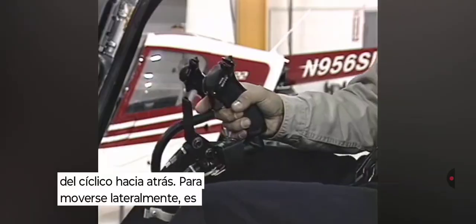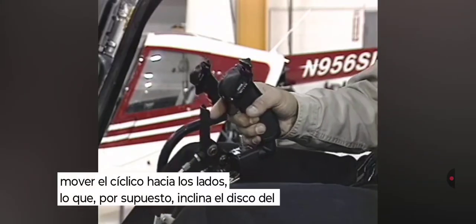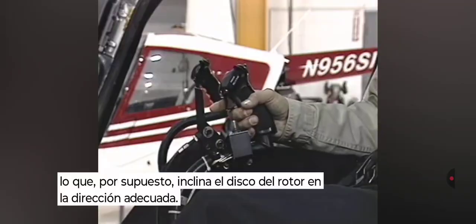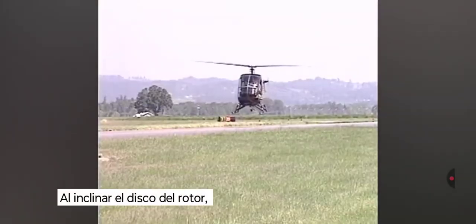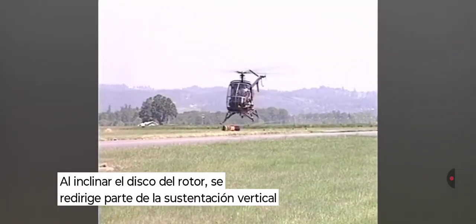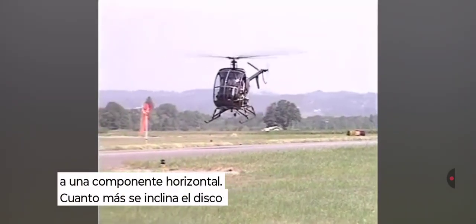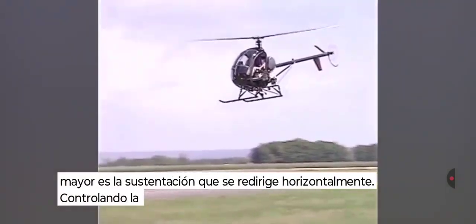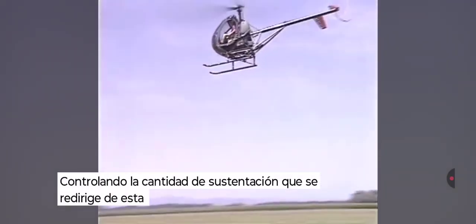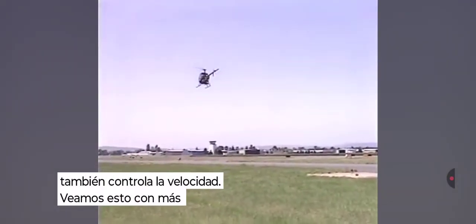Similarly, moving to the sides requires that I move the cyclic to the sides, which of course tilts the rotor disc in the appropriate direction. By tilting the rotor disc, we're redirecting some of the vertical lift into a horizontal component of lift. And the more we tilt the rotor disc, the more lift we're redirecting horizontally. By controlling how much lift is redirected in this fashion, the cyclic also controls airspeed. Let's look at this in more detail.